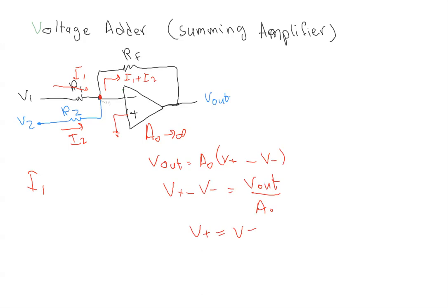It's not a real ground. It's not shorted to 0. We have to stress this thing. So it's not shorted to 0. It's just carrying 0 potential due to the large gain of this amplifier.